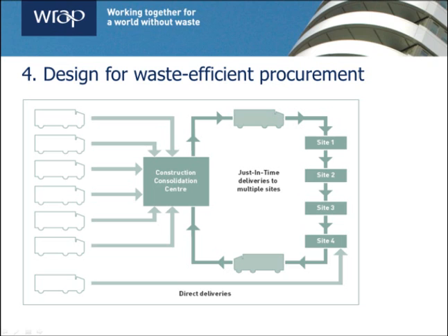However, designers can also take action by considering how work sequences affect the generation of waste and identifying how design choices could lead to the generation of waste. Once understood, waste can be reduced through improved design, specification and procurement. For example, reducing the different types of plasterboard specified will reduce the overall volume of offcuts and unused material.